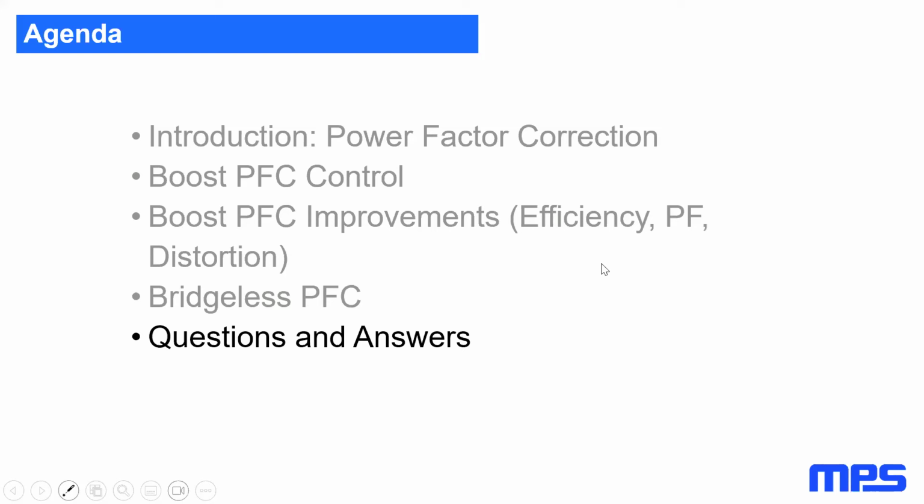Okay, next one is, does MPS have any bridgeless specific IC controller? Yes, at the moment we have one digital CCM totem pole PFC controller, MPF32010, and we're just sampling a new one, MP45000, which is a CRM totem pole PFC for lower power. So at the moment we have two parts here.